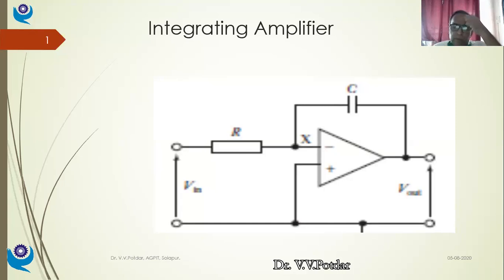If I have got two different sensors, three different sensors, and these sensors are giving the output voltages, and if I want at the summing point of my control system these signals to be added, and if I'm interested in amplification and summation of these input signals, then I can make use of operational amplifier as a summing device. Similarly, if I want the operational amplifier to be used as a comparator, like a subtracting device.